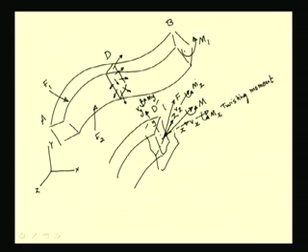This moment Mz and the moment My, along y and z directions, tend to bend the member. So, the moment My bends the member in the plane xz, and the moment Mz tends to bend the member in the yx plane.